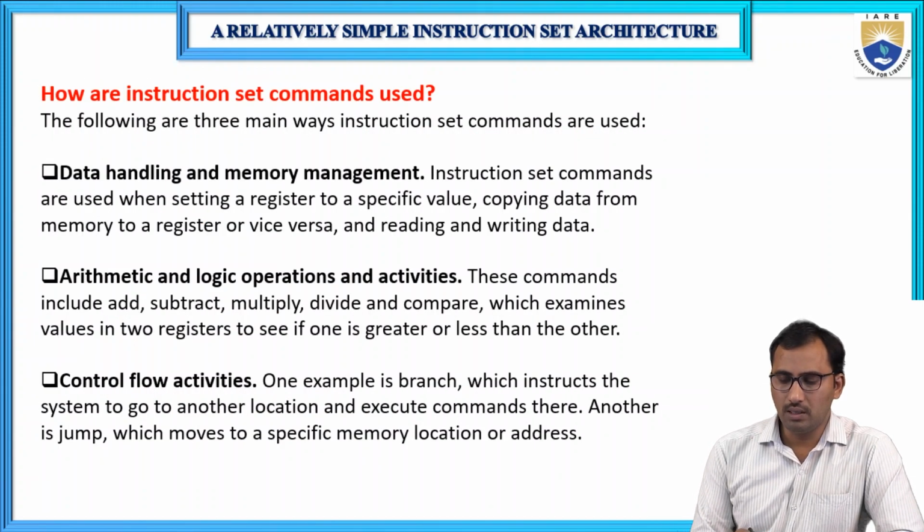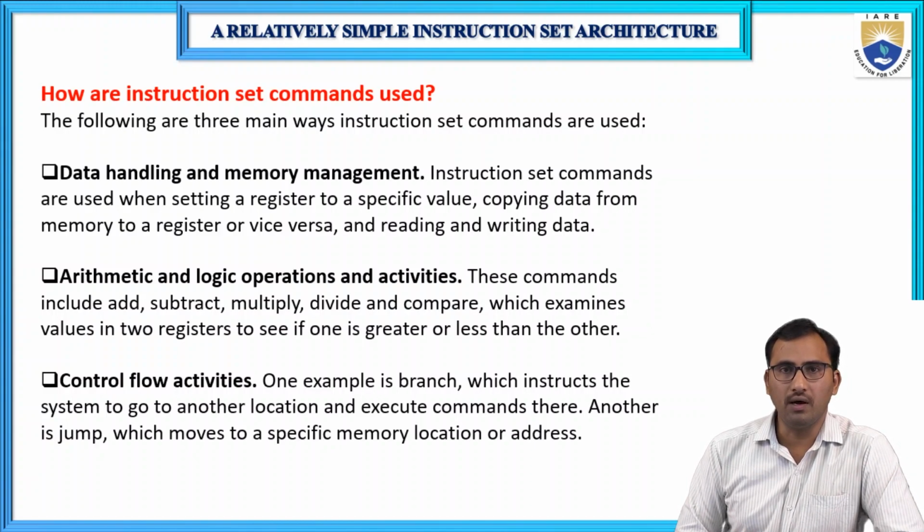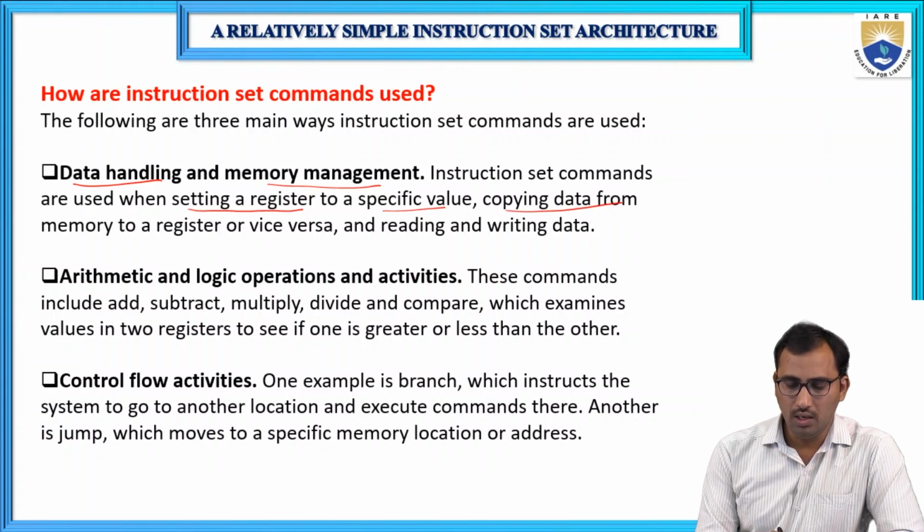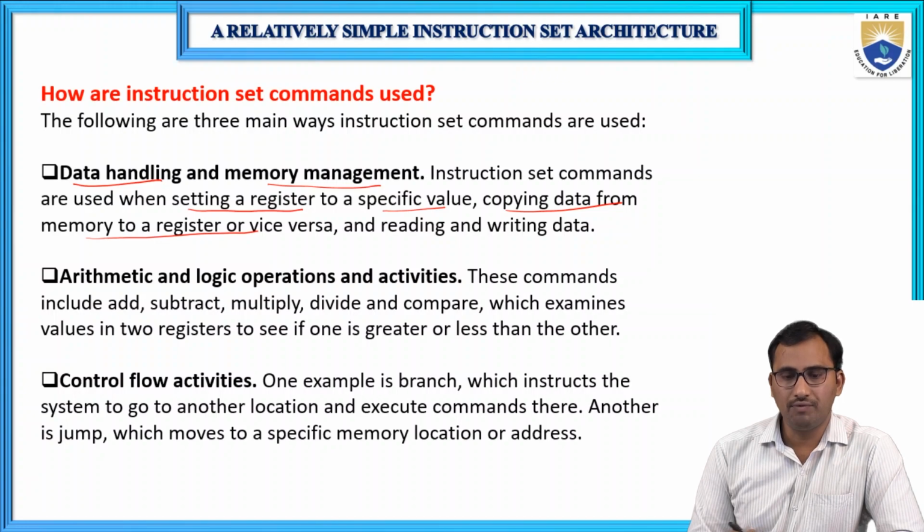So how are instruction set commands used? The instruction set commands can be used for various purposes like data handling and memory management. Data handling means setting a register to a specific value, or copying the data from one register to another register, or copying the data from memory to the register or register to the memory. All these types of operations come under data handling and memory management.